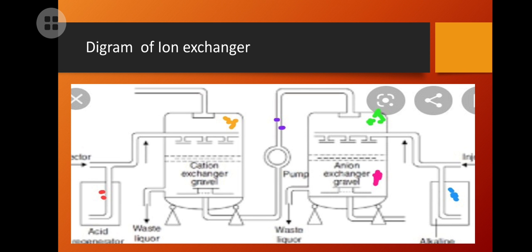Now in the second chamber, where the anion exchanger is, by continuous hardness removal it has converted into R2CO3, RCl, RNO3, R2SO4, RHCO3, and so on. So now the OH has to be restored.